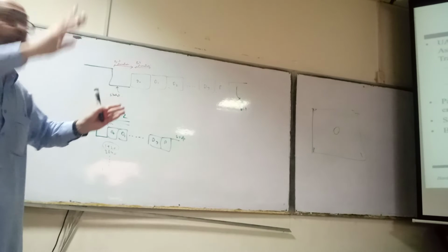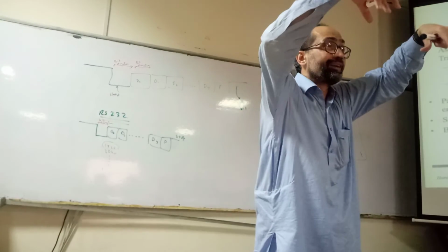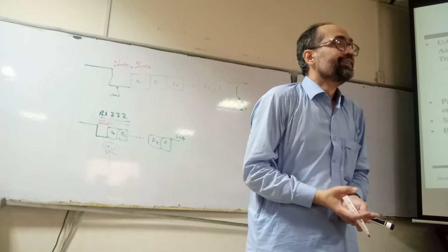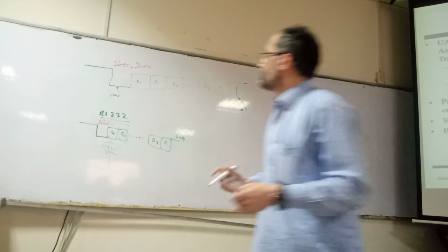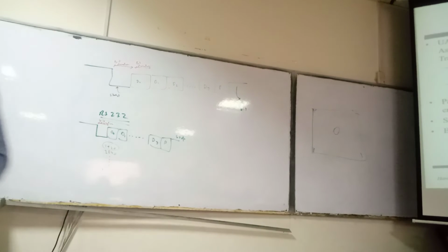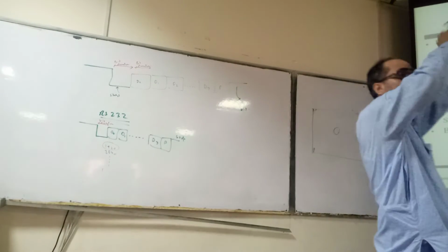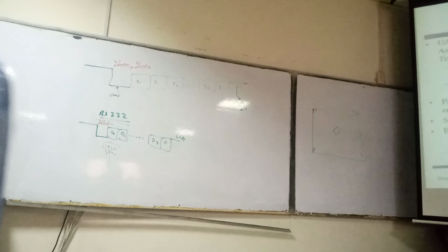Okay, now when you are sending the data and you have a receiver, both the transmitter and the receiver should be configured at the same baud rate. If the baud rate is different, you will not receive correct data. So they should both be configured at the same rate. Now we are at the receiver side, and we want to design a controller for the receiver side. So how can the controller be designed?